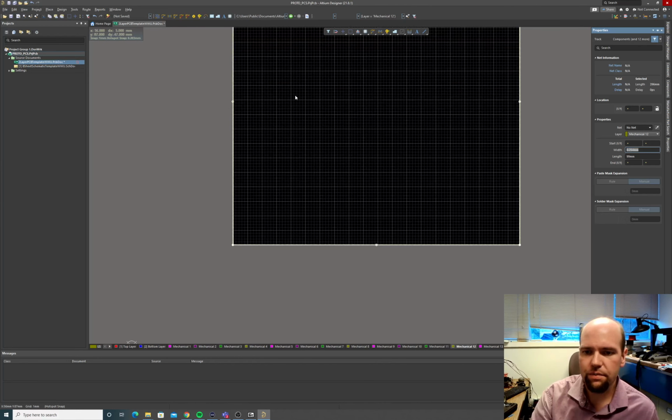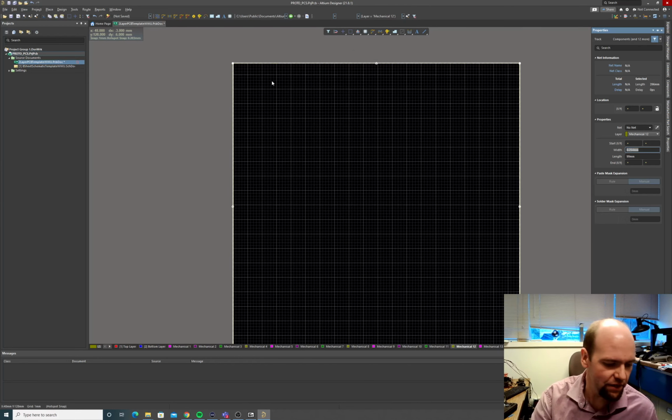You'll notice as I scroll, the grid kind of came back to me here, so that's kind of nice. All right, so let's make sure we're not going to go bigger than we can, because if you submit a file that's bigger than 100 millimeters by 100 millimeters and the fab says we can't do it, what they'll say is we can do it, but it's going to cost $40 instead of $5. And normally what that means is we won't do that. We're not going to pay 8 times as much just because you were off by a millimeter. But the bigger issue is it's going to delay the order for all of your classmates. So when you submit these, you really want to make sure they're under 100 millimeters by 100 millimeters.